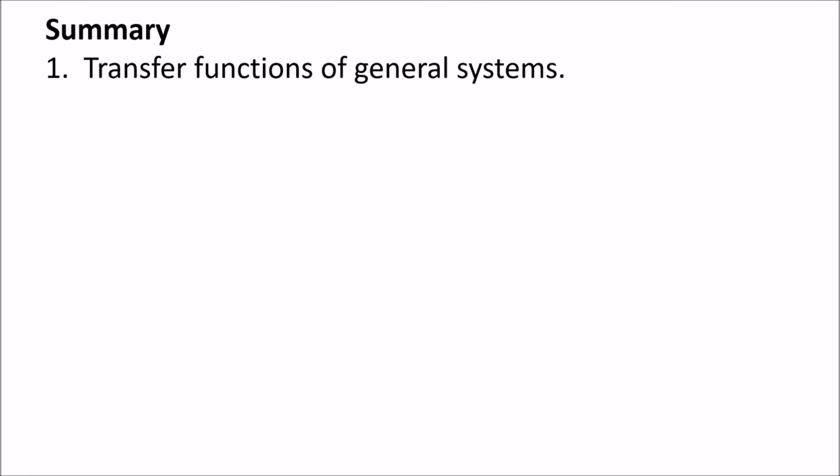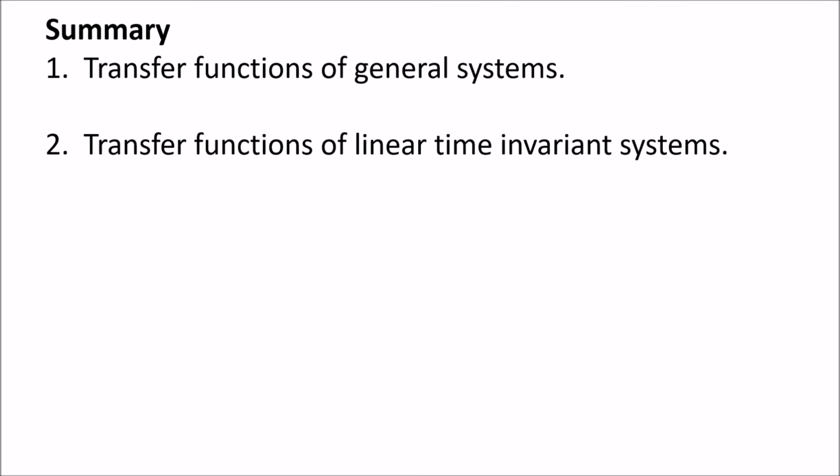Okay, so to summarize what we discussed today, we started off by talking about transfer functions of general systems, and we saw that when you're talking about transfer functions with controls engineers, they might be talking about more complicated nonlinear systems, and really what we're discussing here is the relationship between a given input and a given output of a system. Now, the type of transfer functions that we're more interested in, because we have some mathematical tools to deal with, are transfer functions of linear time invariant systems, or basically transfer functions of systems that can be described using a system of linear ordinary differential equations.